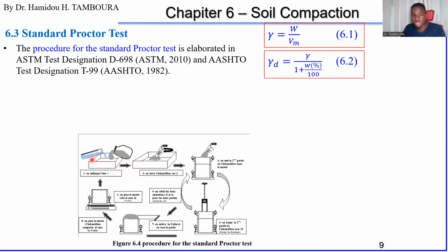It doesn't have to be small like this, but you add the water each time. But be sure that for the first test, don't put too much water, of course, because you will be adding water again and again. So make sure that you have enough soil in this container. Add water to the soil and mix them.